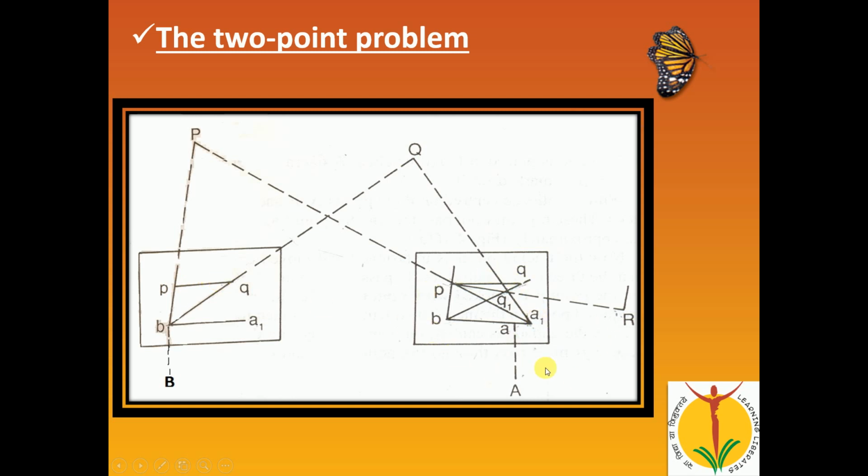A. So first thing we have to do here, alidade touching point P and bisecting the ranging rod at P here, and alidade touching point capital Q and bisecting the ranging rod at Q here. We have to choose one auxiliary point, that is point small b. We take the intersection of lines P and Q at the backside, and that point b we call the auxiliary station, and from this auxiliary station we are going to choose one point capital A, whose position is not known. So here, alidade touching at point b, the auxiliary station, and by eye estimation we are going to take this point A.